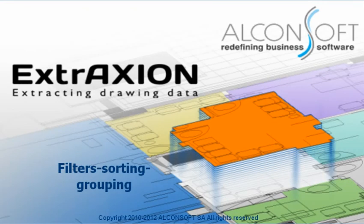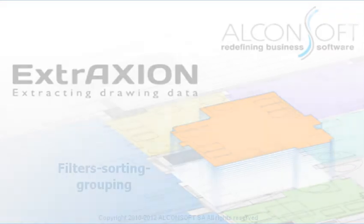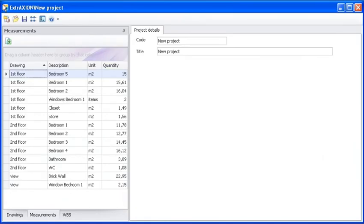This video shows you how to modify the program's tables to hide or show columns, to increase or decrease their width, as well as how to sort, group, or filter the measurement tables, the WBS tables, and the measurement layers. We are going to apply all the above to the Measurements table.